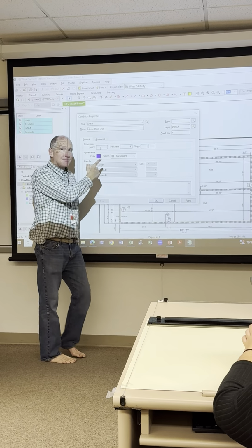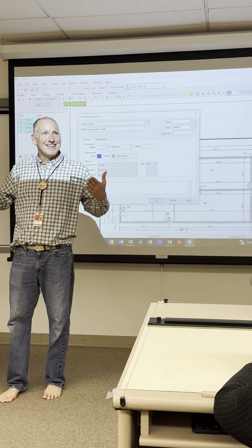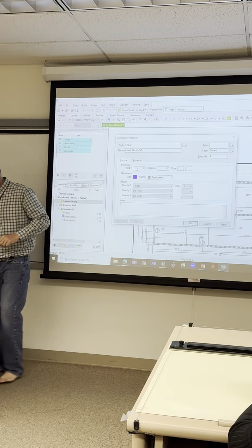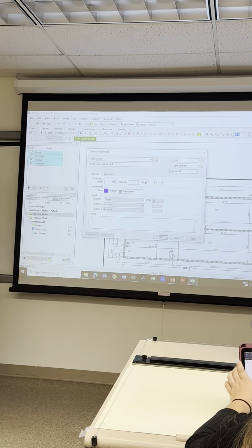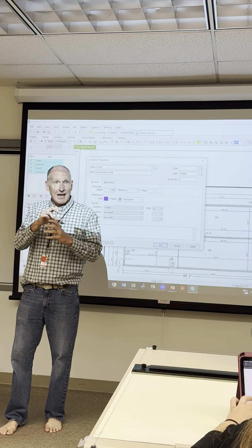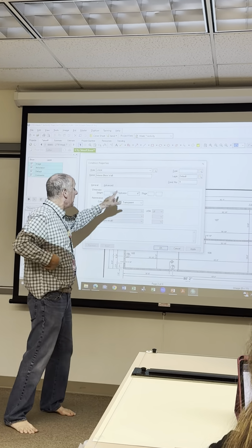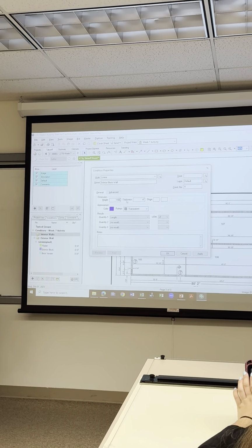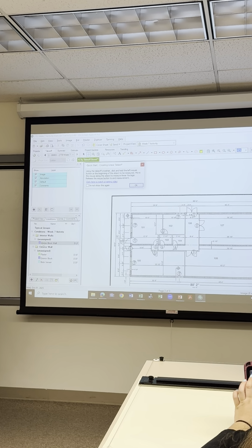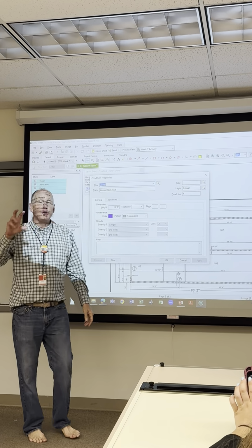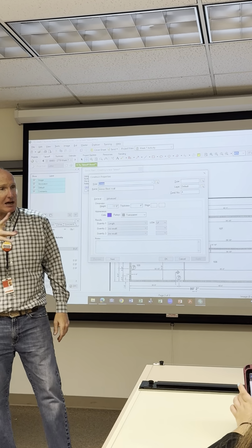See the dimensional height? We know the length. We're interpreting the height from the elevations, 11 feet, and we're going to put an assumption that that interior block wall is 11 feet high. Again, data entry is raw. 1100 is the entry. When we click OK and go back in, it will grab it and say 11 feet 0 inches. Okay? When we do dimensions, enter raw, just like calculating scale.